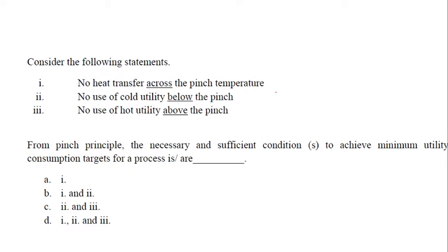And statement 2 is actually false, because the principle that is necessary for the pinch principle is that no use of cold utility above pinch temperature, but here it is written below pinch temperature, and no use of hot utility below the pinch point. So the correct answer for this one is A. Only statement 1 is true.